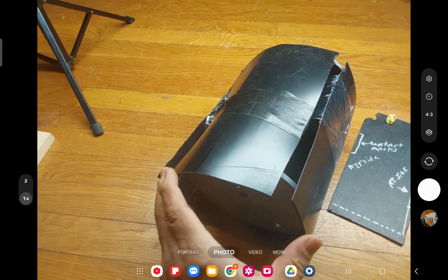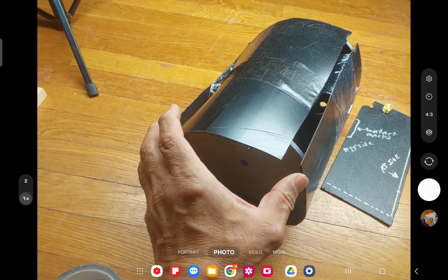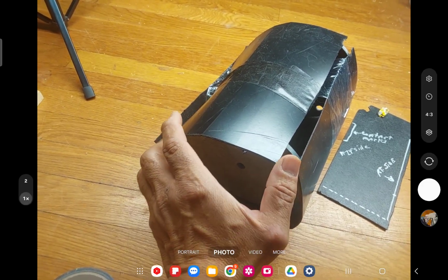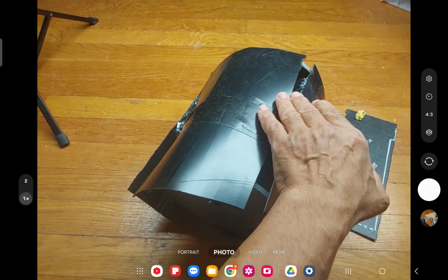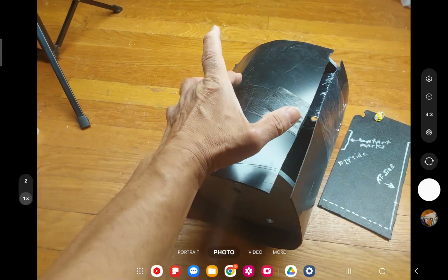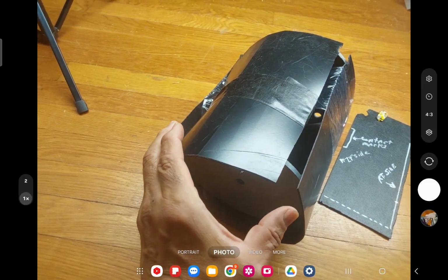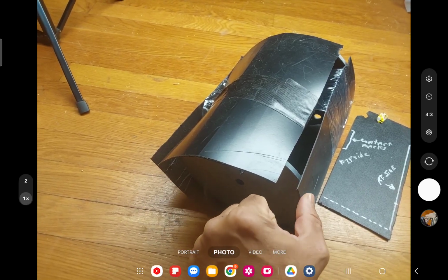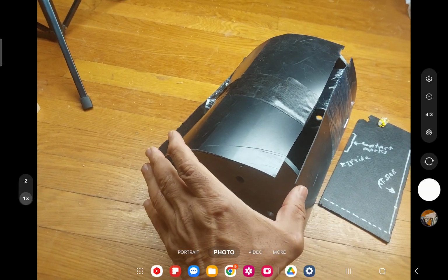All right, once it buckles over there, the pressure out here is 1,000,000 pounds, but it's not equal anymore. See by my thumb here, it's not equal here anymore. Over here, though, it's now got a gap, if you will, a gap in the cylinder that stops this from buckling. That pressure here says, oh, I see the differential, and it rotates. Pivots like that, pulling itself off the interface of the carbon fiber. So here it is here.